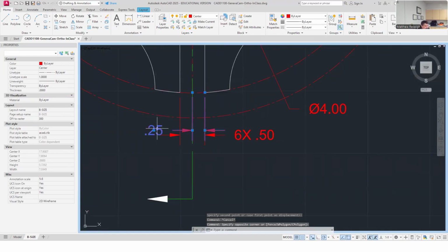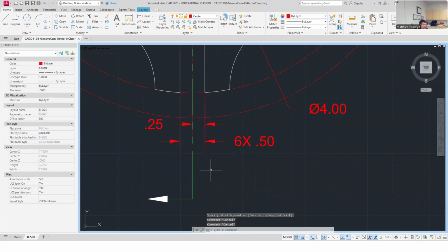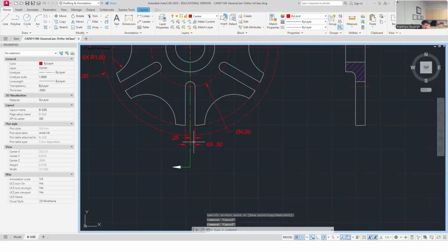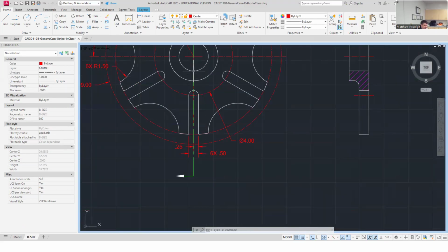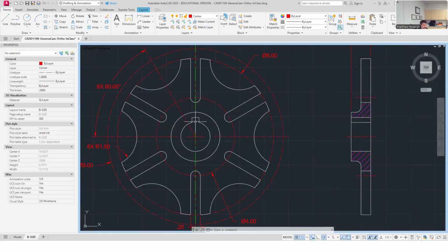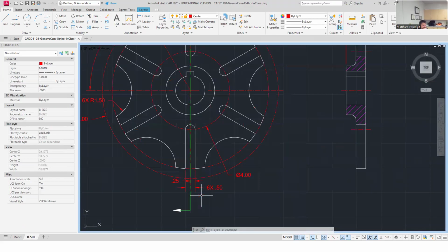I will probably come back and bump these to their correct locations, right? Like 3/8 away from probably that last outside center line. And so I'll come back to those, but I feel like that's sized and located a little bit better now. I've added one additional dimension for the location off center, which is really locking in that this is definitely a control point datum this way. I'm going to need it anyway because this has a keyway, so I'm really going to establish this vertical center line as a control vertical. Okay, good. Those are those features.